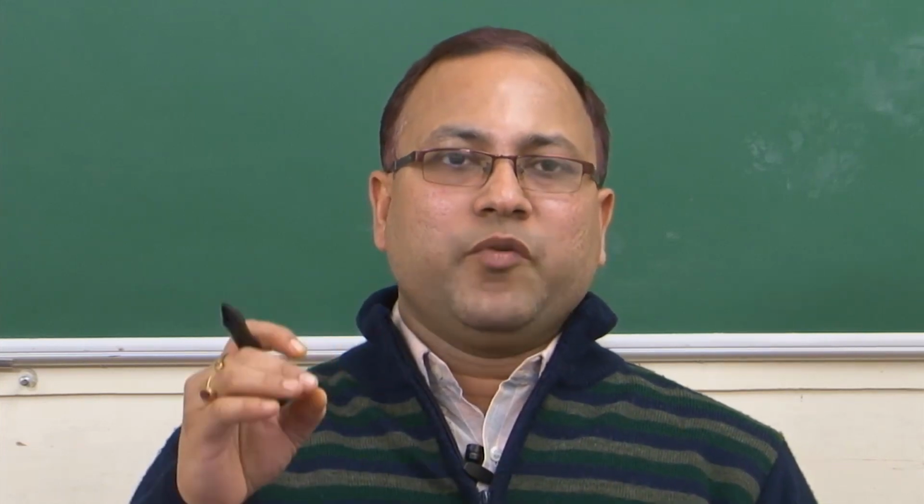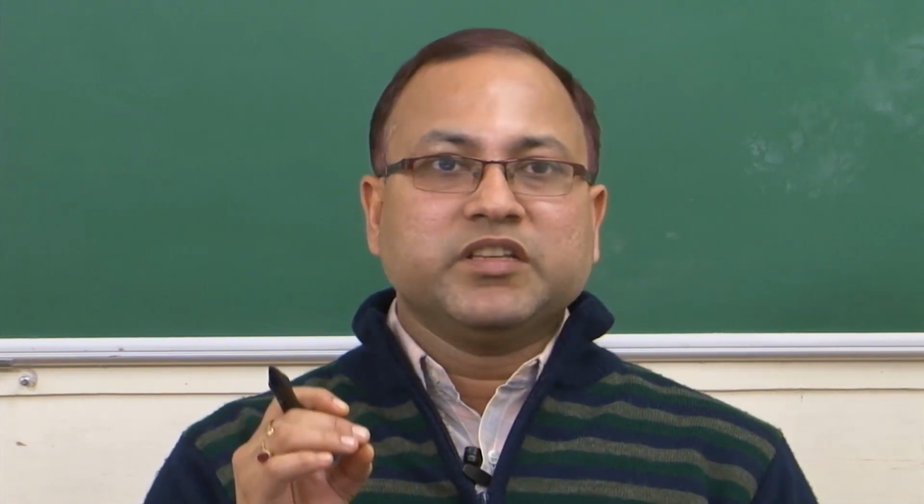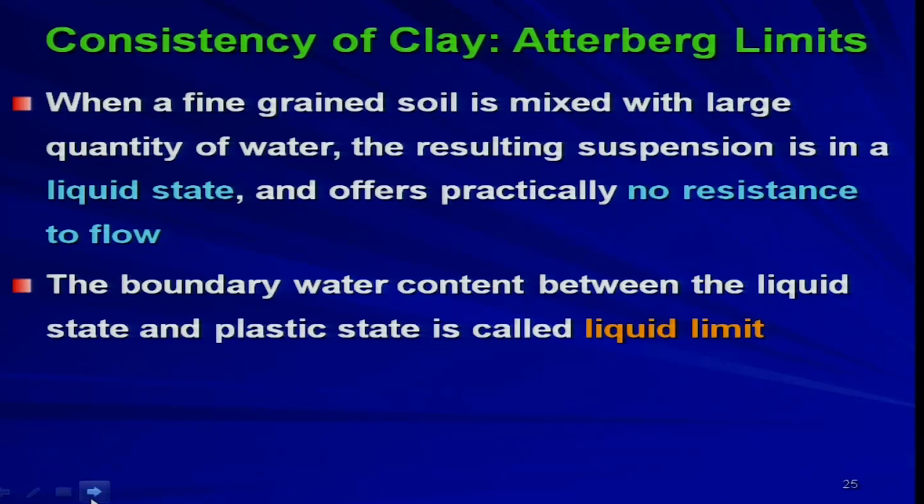So, if you want to construct anything on top of the soil which is on top of this clay soil, which is basically under liquid state, it will not give you any resistance or carry any load. So, that is basically your liquid state. Then the boundary water content between the liquid state and plastic state is called liquid limit.